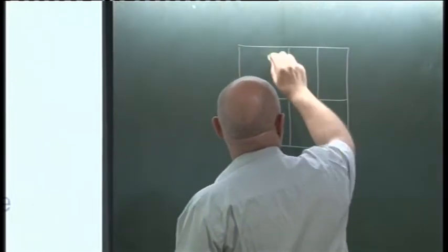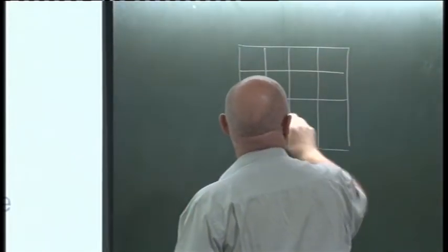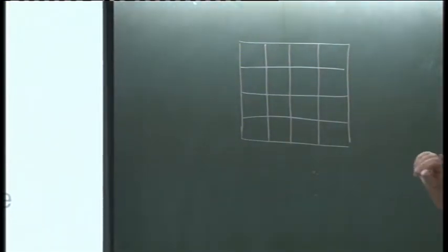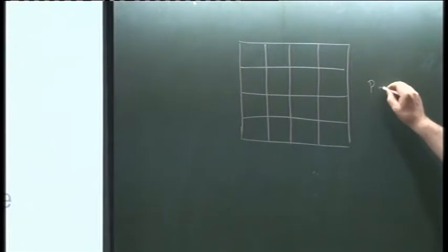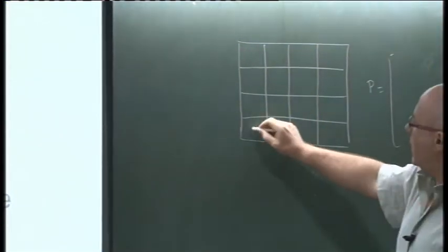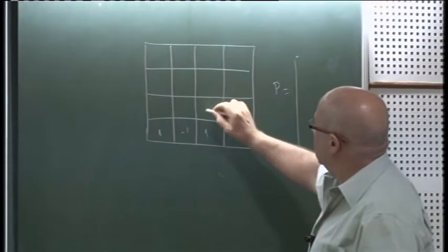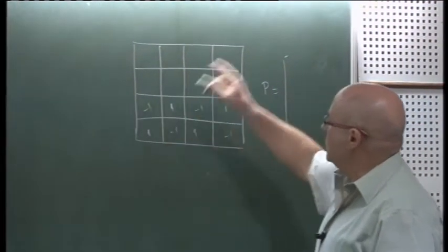It turns out that if you solve a problem in a mesh like that, very structured, why is it not stable? It is not stable for a very interesting reason, because there is a pressure array which is 1, minus 1, 1, minus 1, 1, minus 1, and so on.